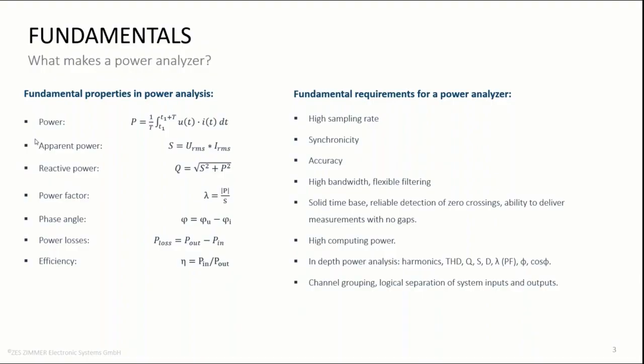So a solid time base is a key requirement in power analysis. In periodic signals, an integration cycle must include an integer multiple of the signal's period. So here, besides the precise time base, a reliable detection of the zero crossings plays a key role. The power analyzer, finally, must be flexible in adjusting the durations of these cycles in order to deliver measurements with no gaps.